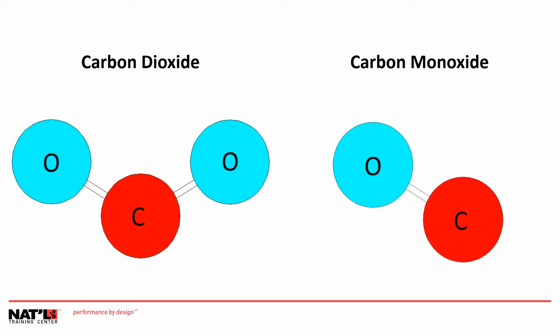The thermal decomposition of oil-impregnated cellulose insulation produces carbon oxides, specifically CO and CO2, and some hydrogen or methane, H2 and CH4, due to the oil. CO2 is not a combustible gas, whereas CO is. The rate at which they are produced depends exponentially on the temperature and directly on the volume of material at that temperature. Because of the volume effect, a large heated volume of insulation at moderate temperature will produce the same quantity of gases as a smaller volume at higher temperature.